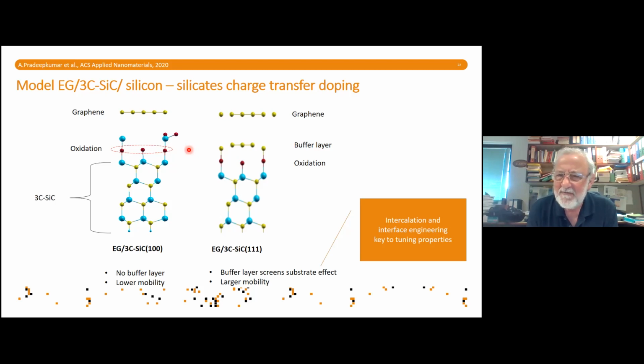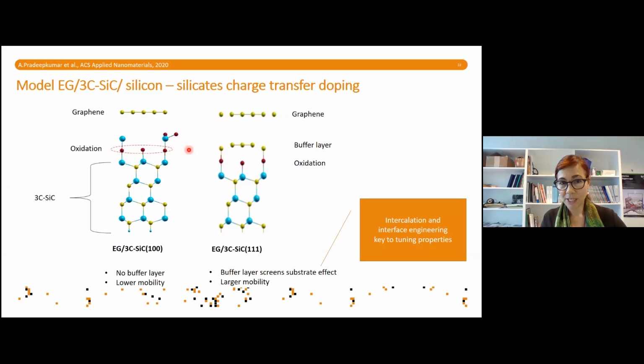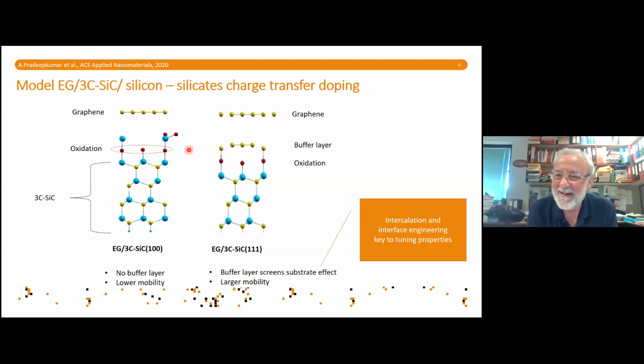I have a quick question, Francesca. It's Laurie here from UWA. My impression is, if you were to grow epitaxial graphene on silicon carbide, are you saying that you would not have grain boundaries? On silicon carbide wafers, you mean? Yeah. You would have much bigger grains. How much bigger?